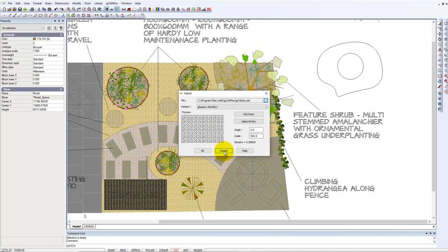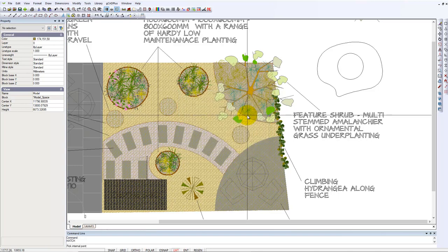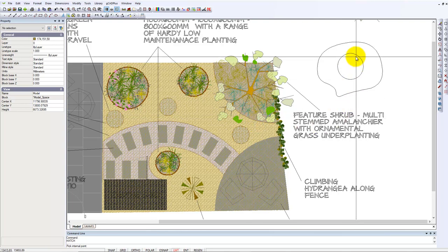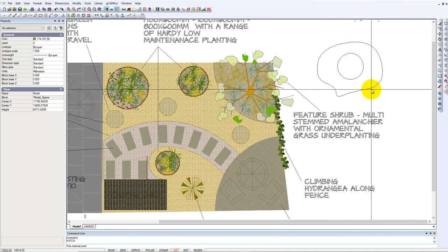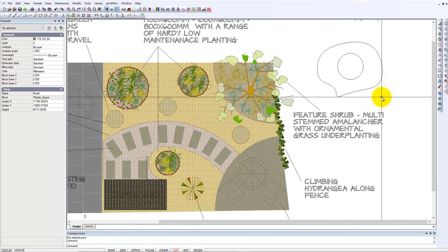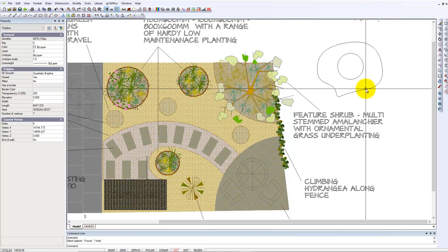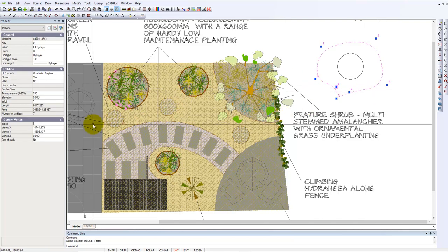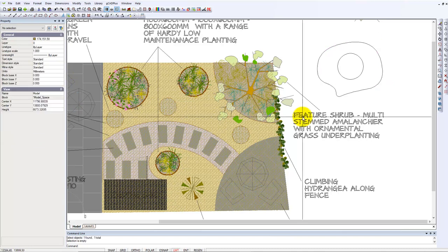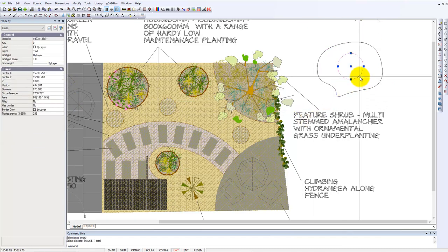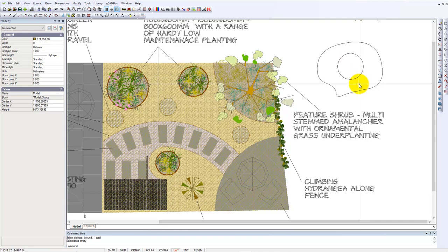There was another option in the hatch pattern. Repeat hatch. We've been dealing with selecting an entity, and that worked well. There is a pick point option which sometimes can be handy, but you do need to be aware of how it's operating. I've got a circle inside of a curve fit polyline. I'll just back out of there and we'll pick this outer one. That's a polyline, and we've applied a quadratic B-spline curve fit to it. And the inner one is a circle, so there are 2 entities there.